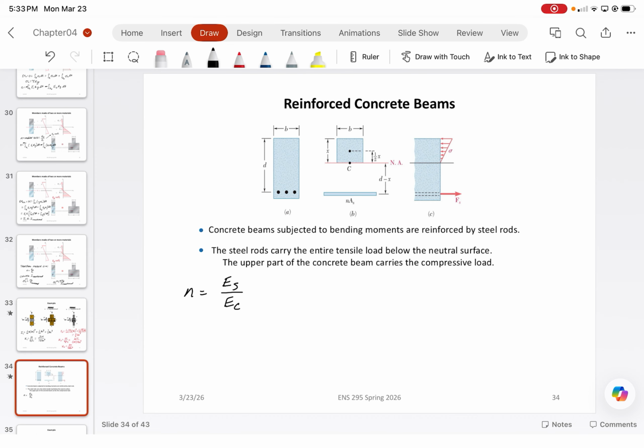Well, we need to use the first moment area, which is just that Q term, which if you guys do the table, should be the A times Y. So to find the neutral axis, we need to calculate Q, which is equal to y bar, which is just equal to the sum of the area y bars over the sum of the areas.